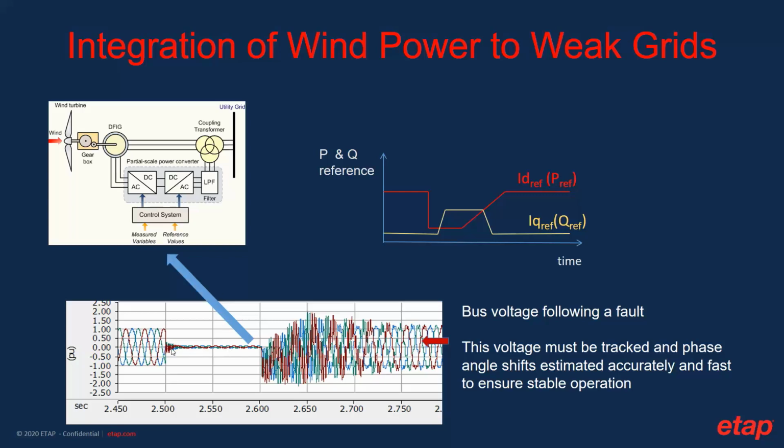When the wind farm is recovering from a fault in this example, you can see that the voltages are not sinusoidal at all. It goes through a transient, there are lots of harmonics involved, and there's obviously voltage ramping, as the voltage builds up slowly. So from a fault ride-through perspective, this time frame is also very important. If the wind farm can stay connected during, let us say, the first 200 milliseconds following a fault, then most likely it would have successfully ridden through this fault.